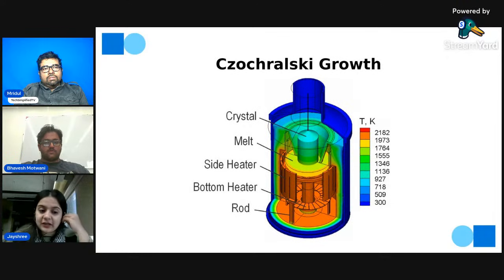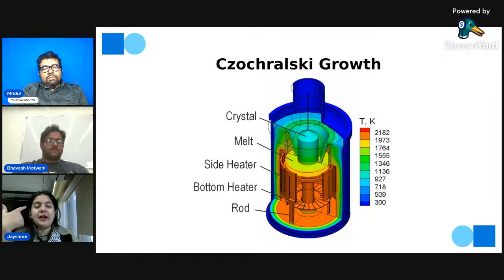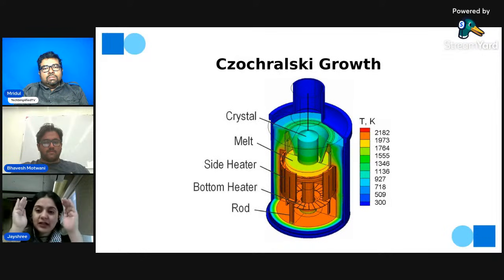Okay, so the susceptor is made of graphite. It is used to support the silica crucible and provides the best thermal conditions. Why is that? Because graphite already has high temperature properties and high purity also, so it prevents contamination of the crystals. It acts like a hot zone around the crucible, as it requires very high purity.